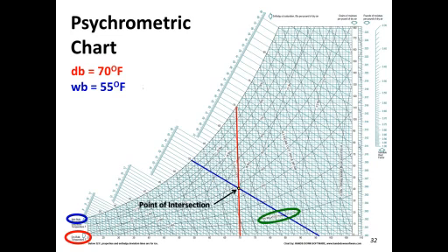Well, that's the relative humidity. The relative humidity, which is circled in green, or is ellipsed in green, that's 10%. Pretty small, but it's 10%. Each successive curve, as you go up to successive curves, you can see the percentage increases. Until I get up here to this one, which is 90%, and you can probably guess that this curve is the 100% relative humidity. So that's what's called the saturation curve.